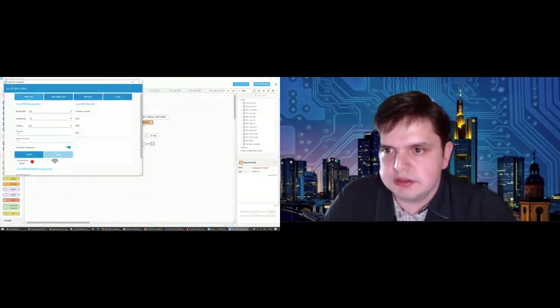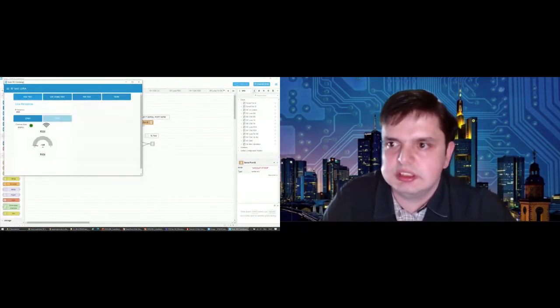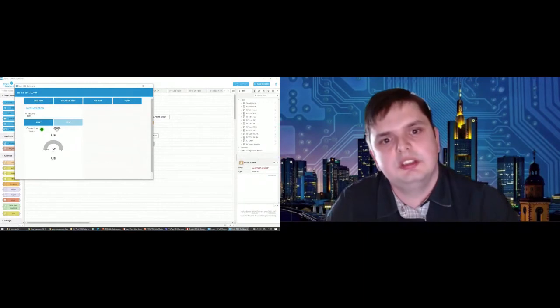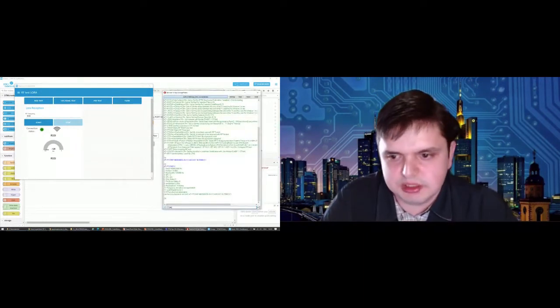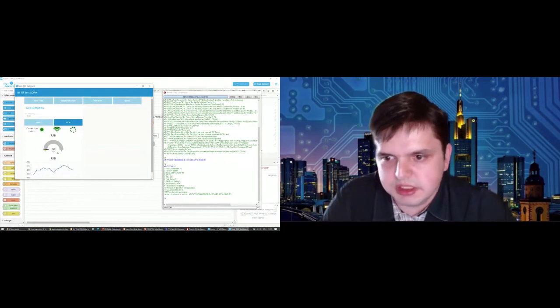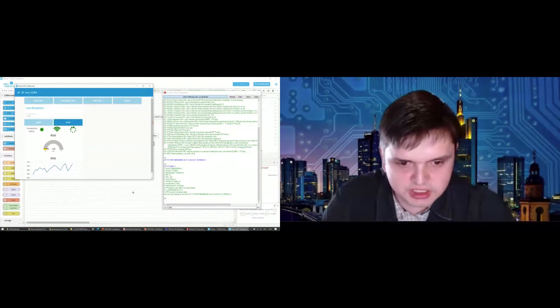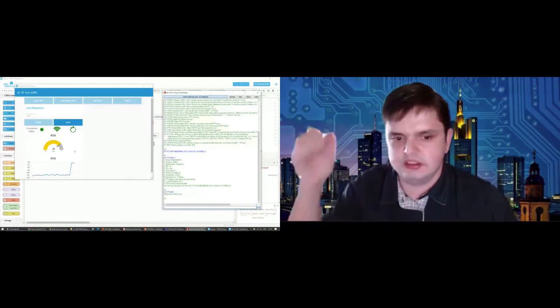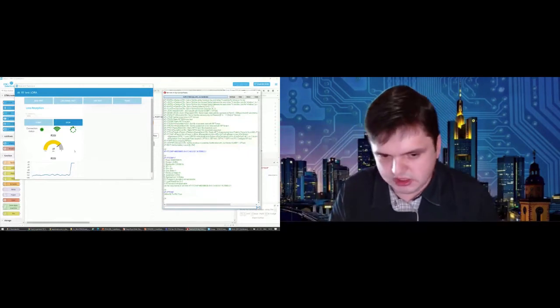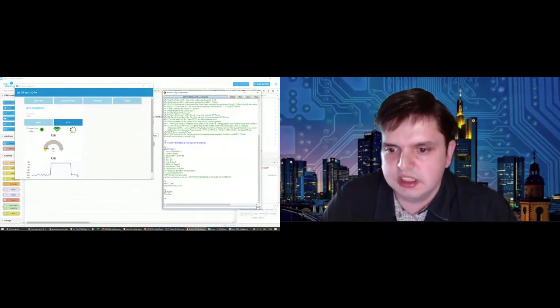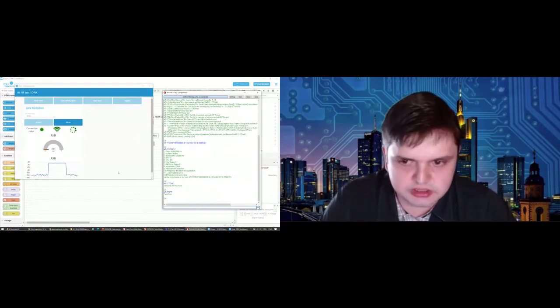Now we are in the main menu for the RF functional tests. If I open also my Termite, I have prepared the AT+TTONE. So on this side, I start the RSSI test. I will see there's basically no signal, minus 120 dBm. No signal is detected. I send AT+TTONE, and suddenly I see the signal is received. If I do AT+TOFF, I will stop the tests, and you can see it rapidly dropped back to minus 120 dBm.